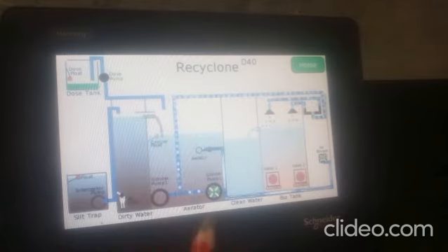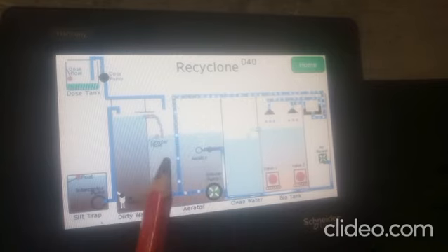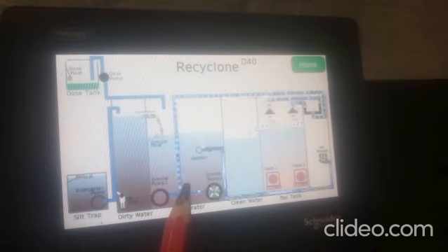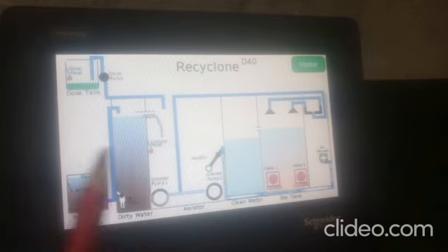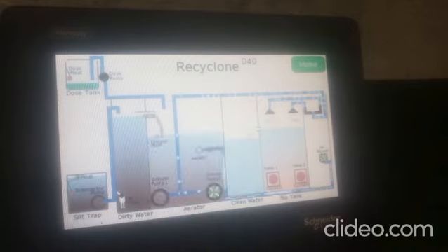In our aerator tank, we have our two grinder pumps, our aerator and our grinder float. In the event that the float is low, this animation will show. Both of the pumps will cease to work as there is not enough water and won't come back until the float up here is activated. This also shows which of the two grinder pumps are running at one time.